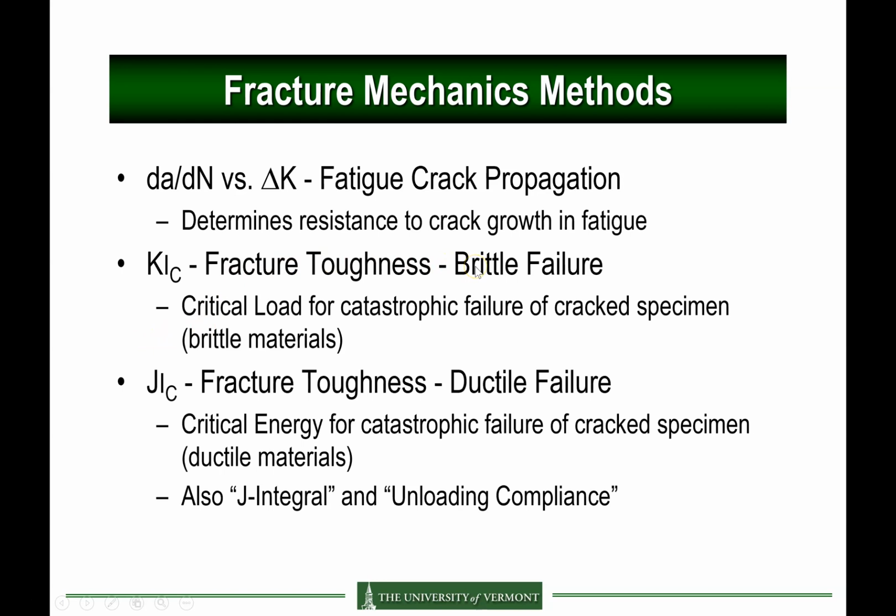And we're going to assume here that the material is quasi-brittle because you operate at room temperature. However, because we are testing aluminum, which is a very ductile material, we may be borderline here with this theory. So maybe aluminum is not the best material to test brittle fracture mechanics, but the analysis is a little bit more simple than the second one.